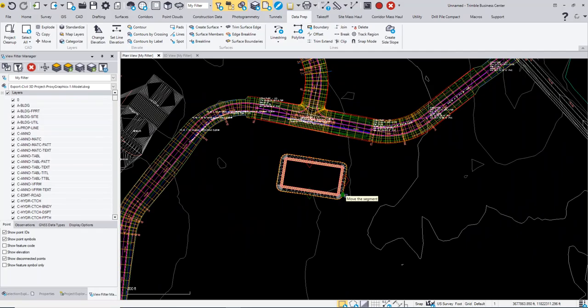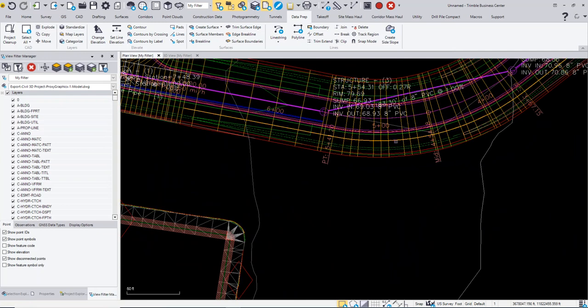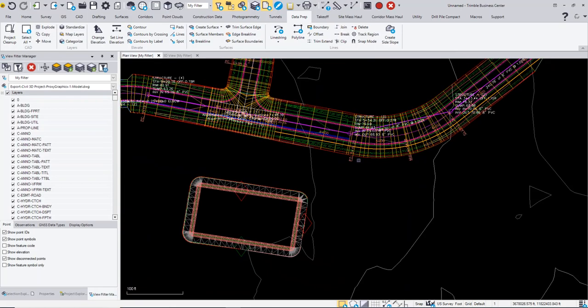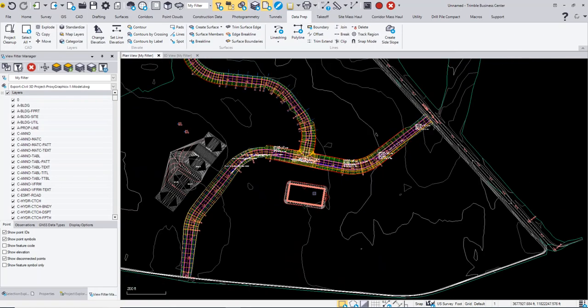With the export option, you maintain the elevation data but lose the curve geometry. So it's going to depend on what information you have. Now, the majority of these feature lines are actually just lines that are tessellated through the sample line, so they're not true curves anyways. That's just something to keep in mind.